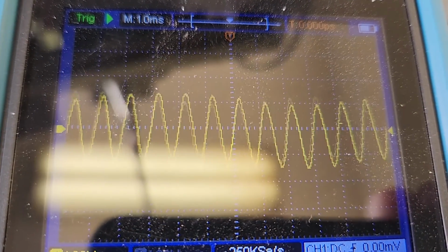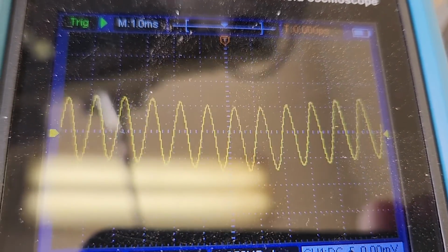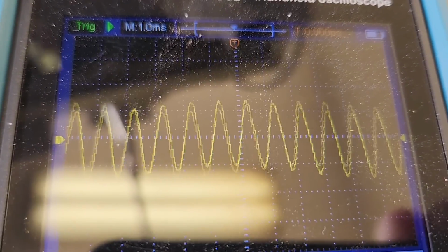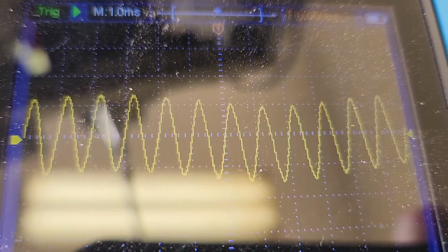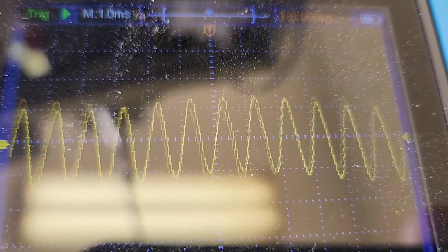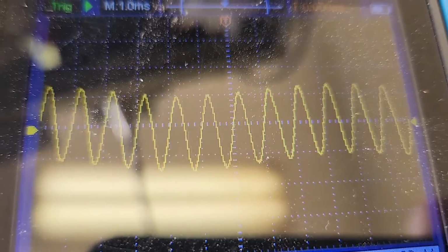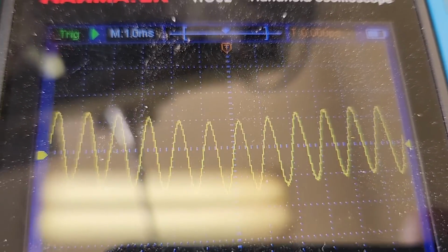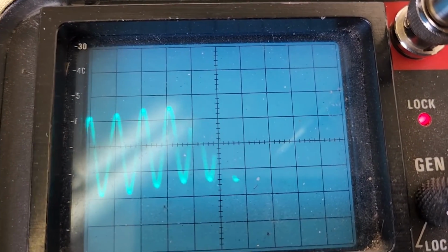And when you're looking at the audio coming out of your receiver discriminator, typically it's discriminator audio. In some instances you may need to use volume control or line level audio, but typically it's discriminator audio. You want to make sure you've got a good clean sine wave before you go any farther, and thus in your end results, you make sure you have a sine wave all the way through. So again, there's your sine wave coming out the other end there.